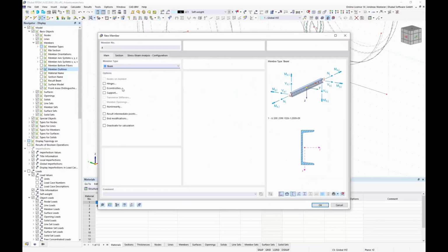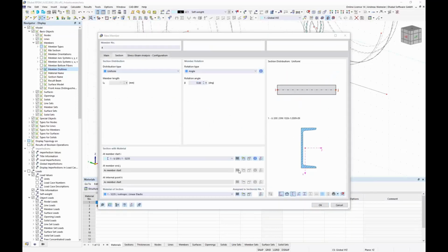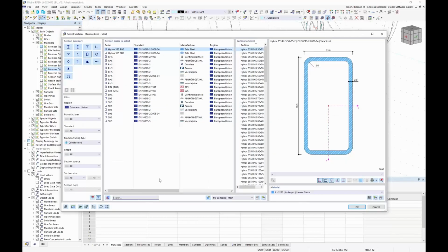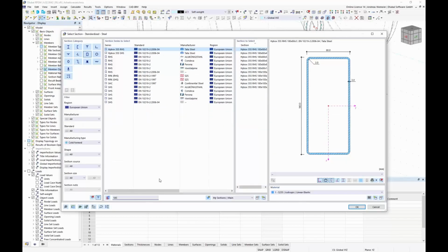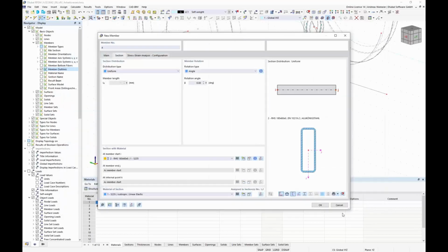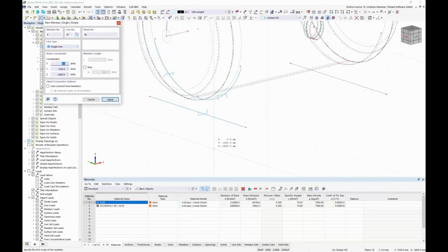In the next step, we have to connect the bottom member with the arc member. For this I also use a member with a hollow section, a rectangular hollow section. The size should be something like 180 by 60 millimeters. And you see, when I use this keyword search, the program gives me all possible solutions considering the filter here, and I select this cross section, and finally I can connect the line.